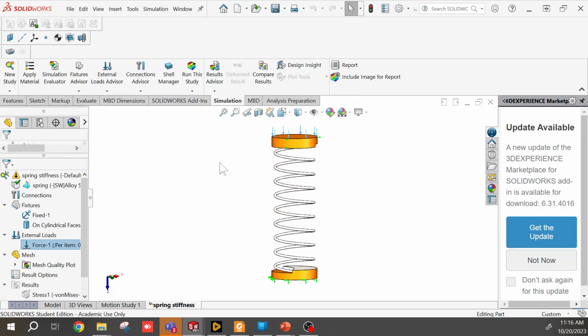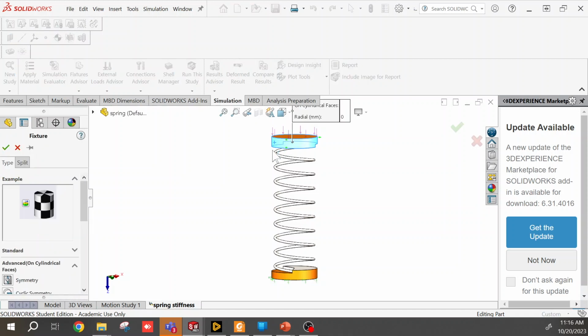So in this case, if you're pushing down here and you're holding it here, it's fine the moment you start pushing down, but the moment there's any movement here that isn't perfectly symmetric, that thing's going to want to fly out to the side. Okay, so we need to force it to move only up and down. So we're adding what I call an additional cylindrical constraint on this top face here to force it to move in this kind of cylindrical path.